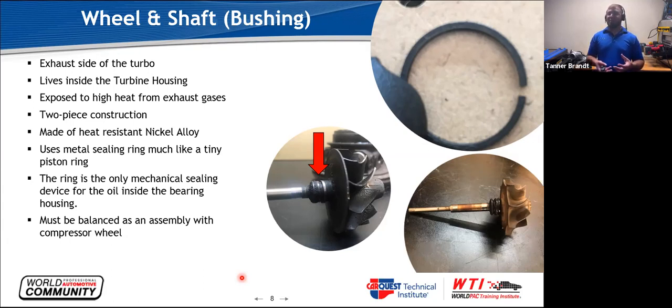One thing that can happen is the exhaust side can coke up and the oil can start to turn into carbon. When that happens, you can see where this arrow shows the ring is really loose. That's not good. This is basically poor maintenance, and a couple other things we'll talk about. That carbon is really hard because it's basically getting hot exhaust air blown over it. So think about taking graphite or carbon, grinding it up, and then continually spinning something through it at 200,000 RPM. It ruins stuff, even nickel alloys.